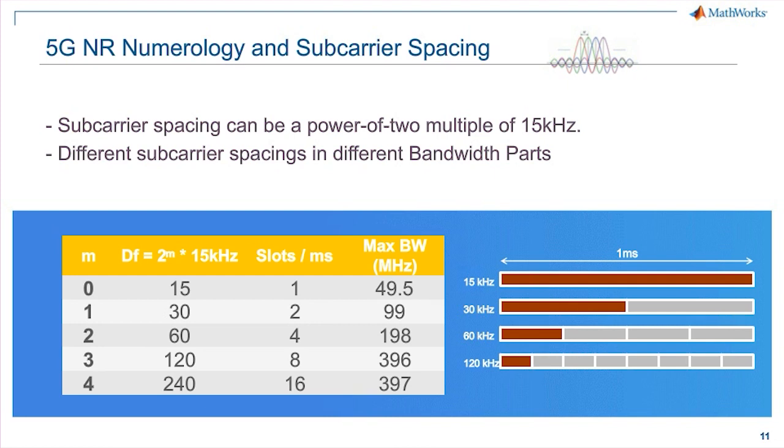Imagine, just by allowing larger subcarrier spacing, you can double, quadruple, and so on your bandwidth, because the same data going over subcarriers that are larger essentially takes you over a larger bandwidth. But because of the time-frequency duality, if you're using a 15 kilohertz subcarrier spacing, the numerology that we're talking about is that we define a 1 millisecond time span of transmission of a 15 kilohertz subcarrier spacing as a slot. This is because a subframe in 4G doesn't call it slot. The minute you go from 15 to 30, the slot divides by half. So shorter time span, larger subcarrier spacing, and so on.